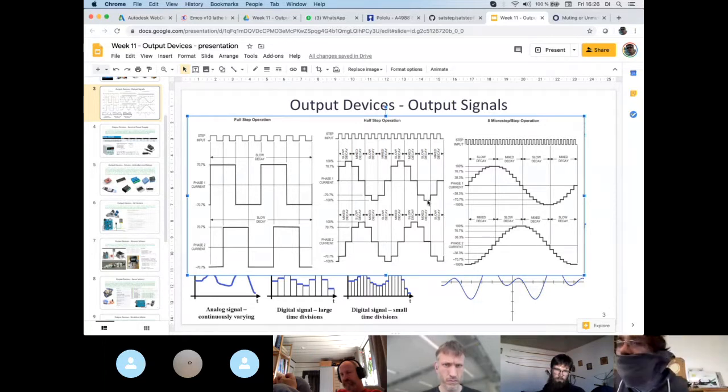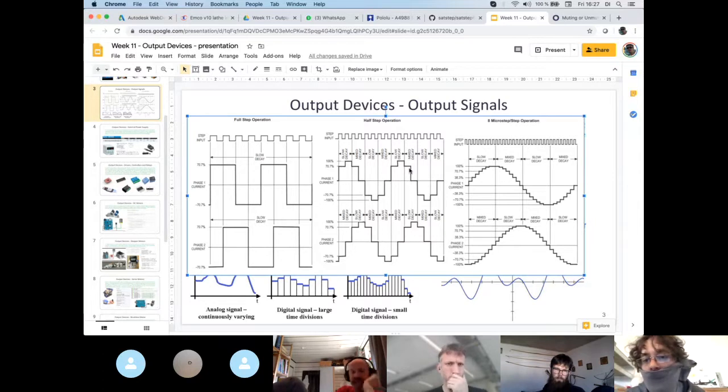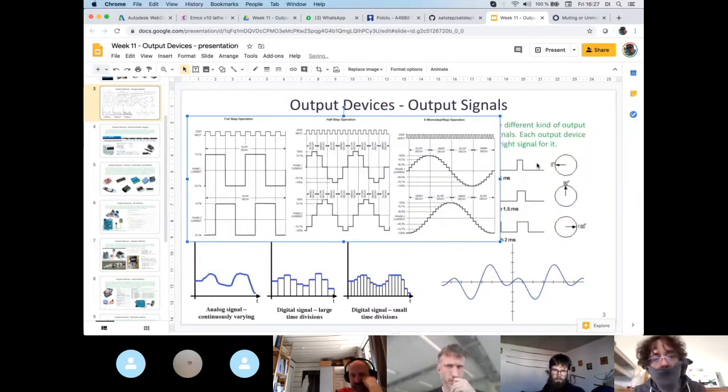This is logic inside the stepper driver, guys. You don't have to care about this because it's rather complex to generate. So therefore, you don't send anymore high and low, but you don't go immediately to 0 because you still have current inside. So you have this kind of wave at the end. So at the beginning, the decay is fast and then slow. So at the beginning, it drops down fast, and then it's slow after a certain time. Yeah. So it's rather complicated, let's say that.